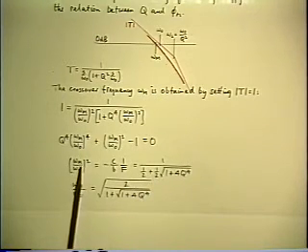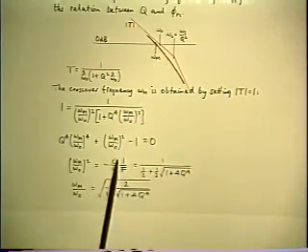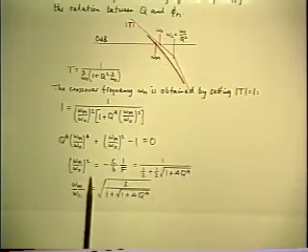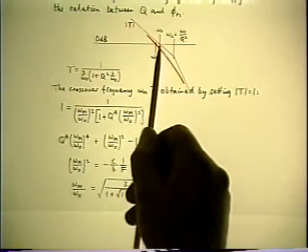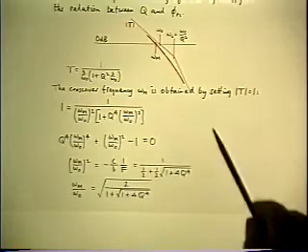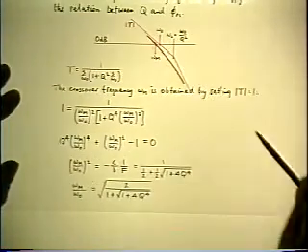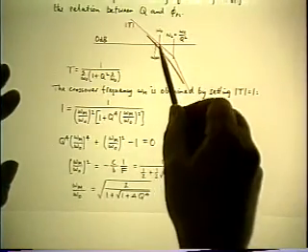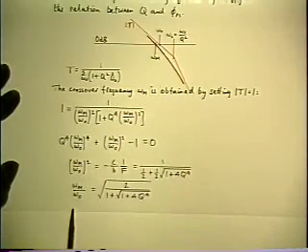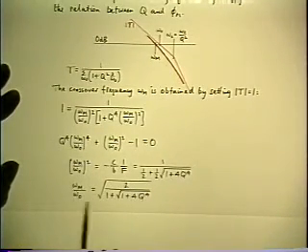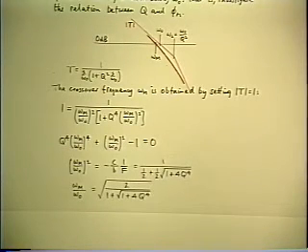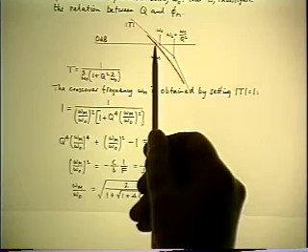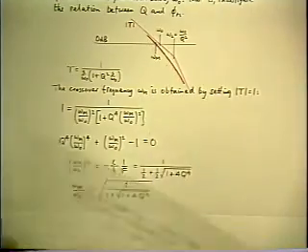So this is the result for the crossover frequency relative to omega 0 as a function of Q. Check that it goes to omega 0 if Q gets very small, because if Q gets very small, this corner moves off to the right, and omega m ought to approach omega 0, which it does. If you let Q go to 0, the ratio goes to 1. Okay, all that's left now is, now we have solved for omega m in terms of the position of the second pole, and now